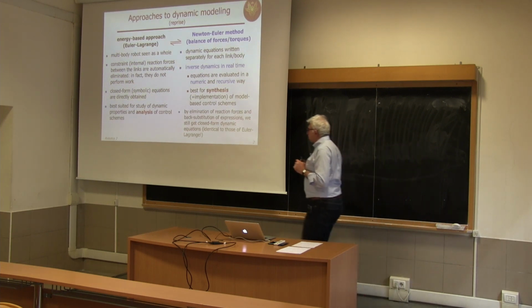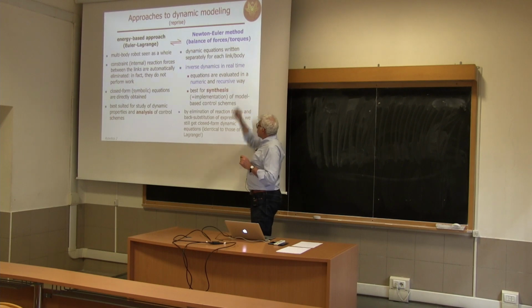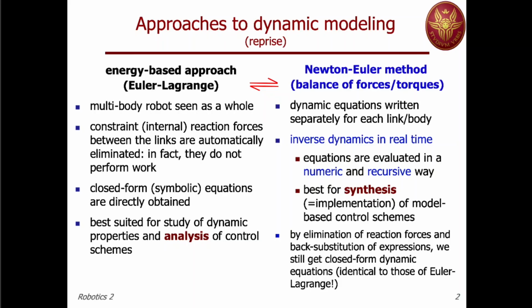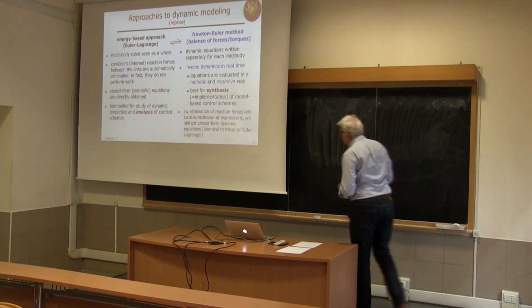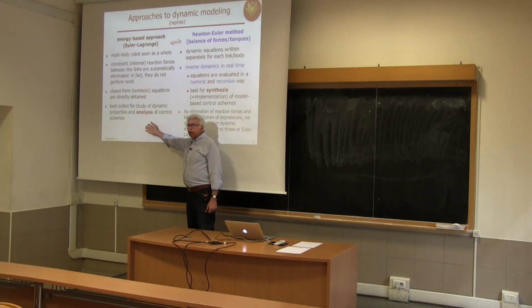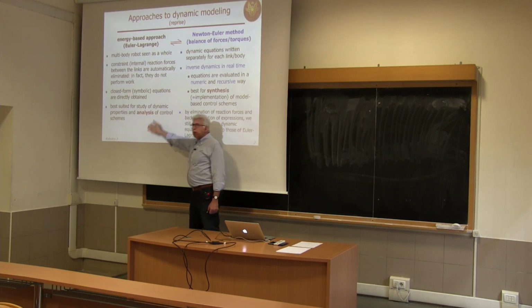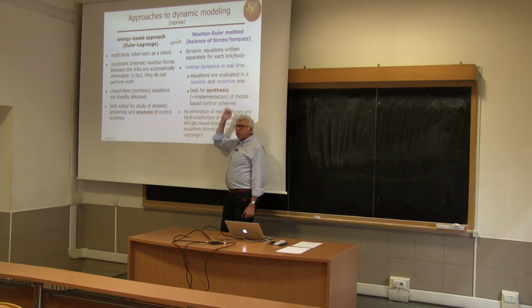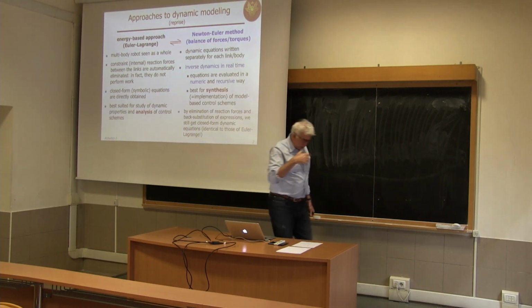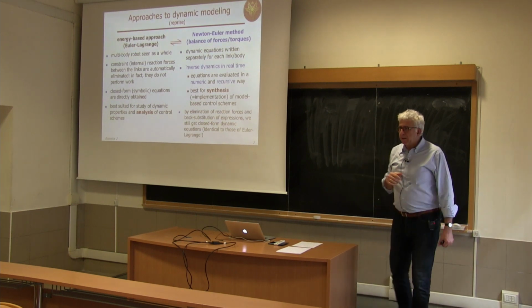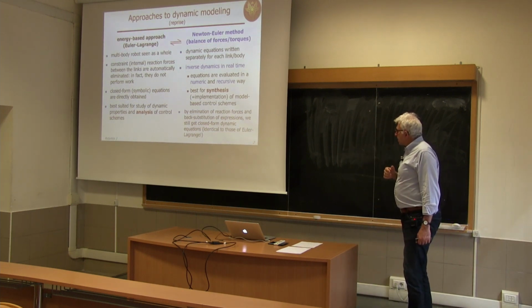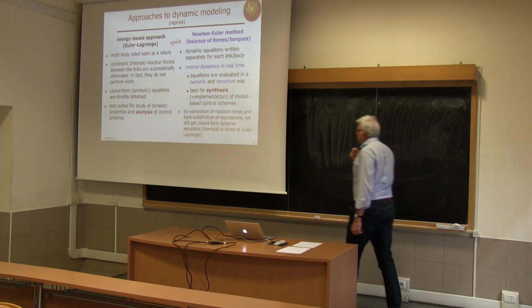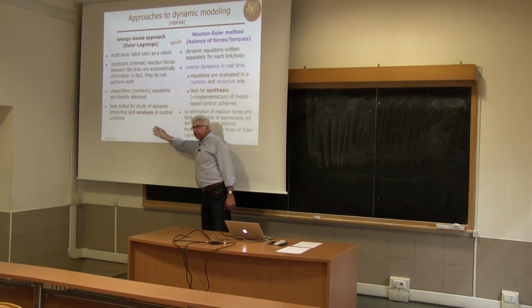There's another aspect which is important, other two aspects. Because we do this in an efficient way, every time we need to evaluate a model-based control law, so a control law that uses the information on the dynamic model of the robot, we will synthesize this control law, although we may have designed it looking at the Euler-Lagrange equation. Once we realize what we need from the model, we compute those terms, or all terms, using the Newton-Euler inverse dynamics, or a set of these equations. We will see this in detail later in today's lecture. And this is one aspect. So good for synthesis as opposed to good for analysis here.